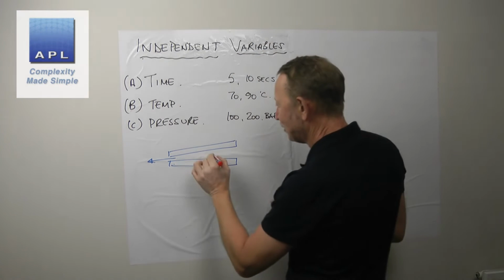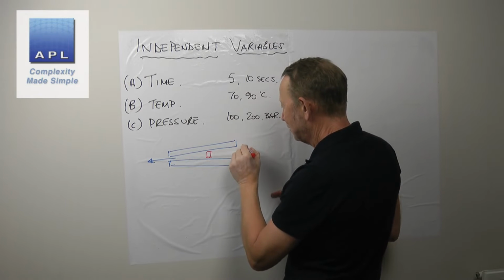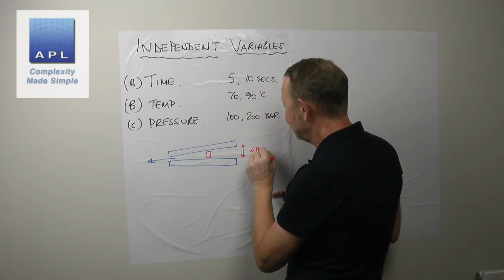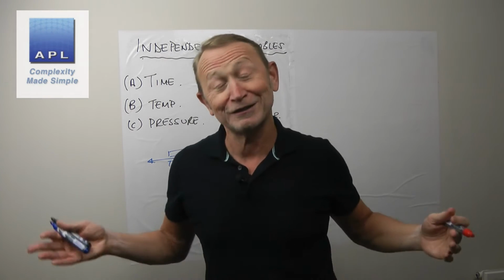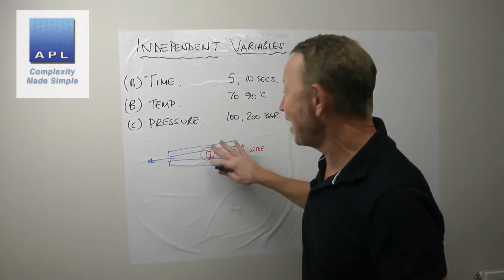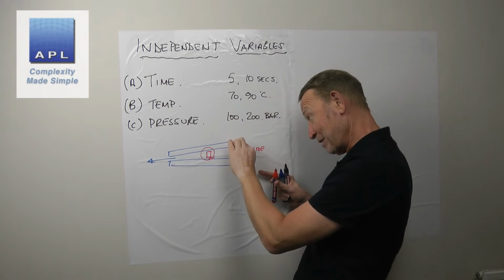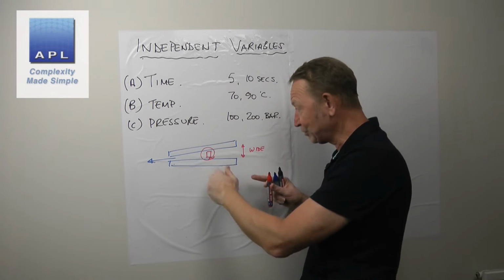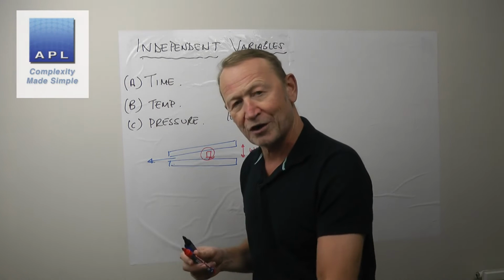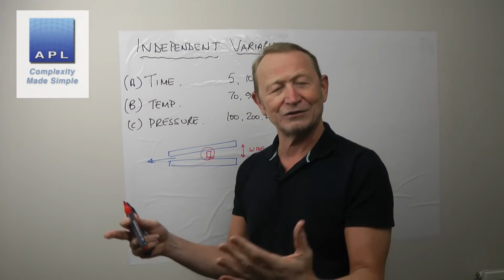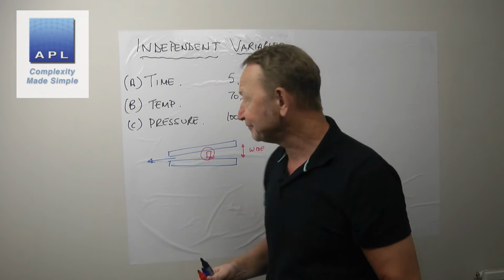And we reached a point where the diameter of the component was small, but the settings were wide, what happened? The part falls through the rollers. Of course, it can't drive through the machine. They are not independent of one another. So they could be independent, maybe, if I'd used different numbers. But if you use the wrong numbers, you can't set the small diameter with the wide angle on the rollers. That's not independent. And that's what we're talking about.